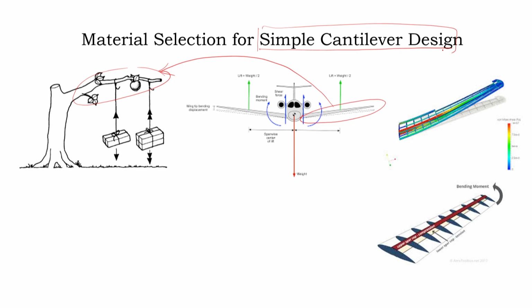in its elementary form. Of course, there are many complexities there. For example, you would see there is a main part, then there are spars there which are used to maintain the shape of the aerofoil, and according to that kind of a shape you will get a variation of load. But at the core these two resemble each other, that they are essentially simple cantilever beams to begin with.